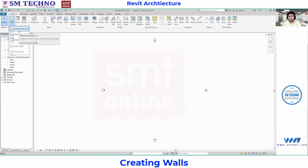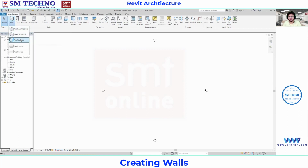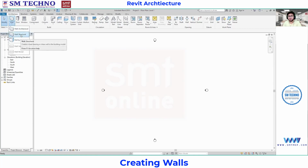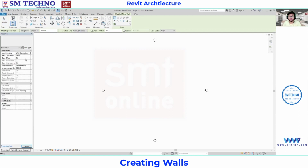Wall architectural is the type of wall we are working with. Wall structural is also there, wall by face is also there. Wall by face we will see in chapter 6. Wall structural is the scope of a civil engineer whenever they go with Revit Structure. So anyhow, we will go with wall architectural. When you select this one, now you will get a property. Can you see the properties toolbar?